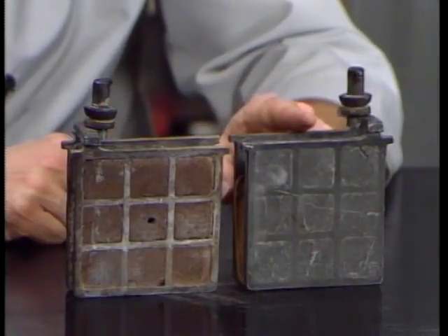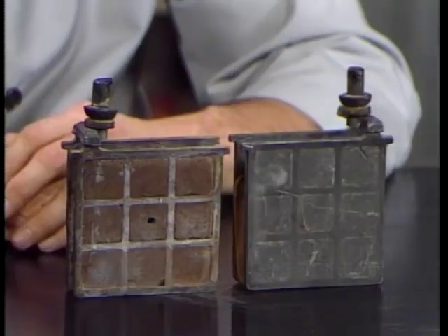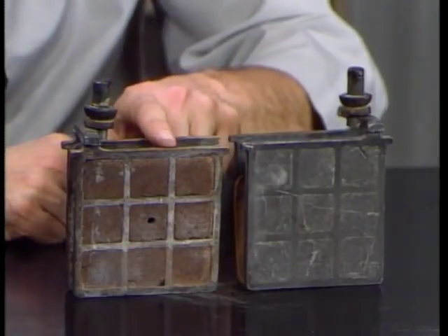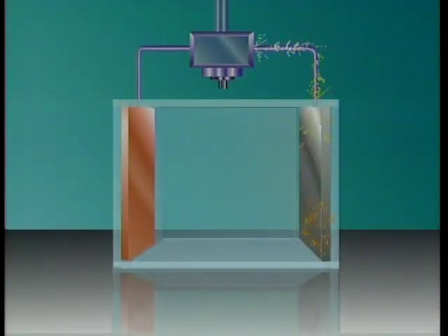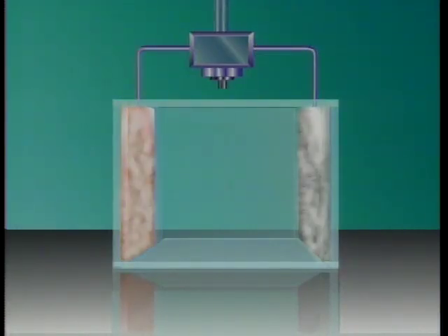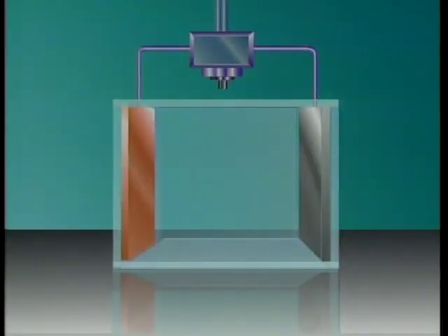In use, a reaction forms lead sulfate on both electrodes. Atoms on the lead electrode are oxidized to a white coating of lead sulfate. Lead dioxide is reduced to lead sulfate. Electrons released from the oxidized lead can do work, such as turn a car's starter motor. They travel on to the lead dioxide and reduce it. White lead sulfate gradually coats both electrodes. To recharge the battery, an alternator pushes electrons in the opposite direction. The chemical reaction reverses, and the battery is recharged.